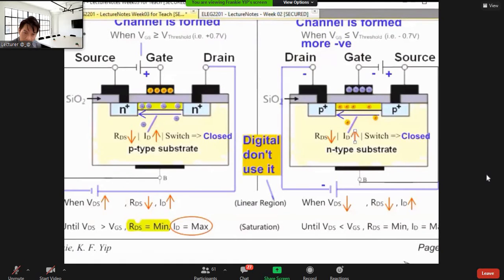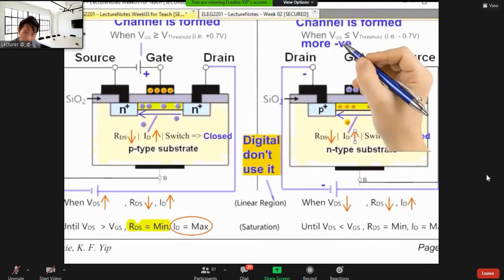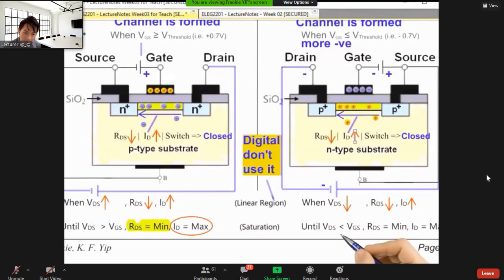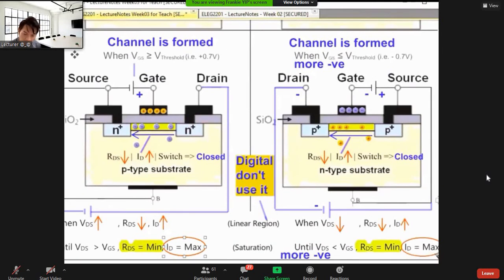Okay. So once again, R decreases and ID increases, so the switch is closed. But once again, we are not going to use the linear region. We are going to use the saturation region. That means VDS is much more negative than the VGS to make the RDS minimum and the ID the maximum.